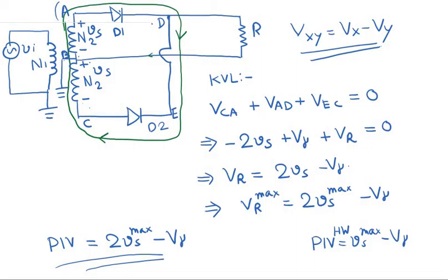Okay, this is actually a disadvantage because, as I said earlier, the diodes which have a higher peak inverse voltage rating, or diodes which can actually endure a higher peak inverse voltage, generally have a higher cost. So this increases the cost of construction of this circuit. And the second disadvantage is that note that the secondary winding here actually has twice the number of coils than was earlier required.